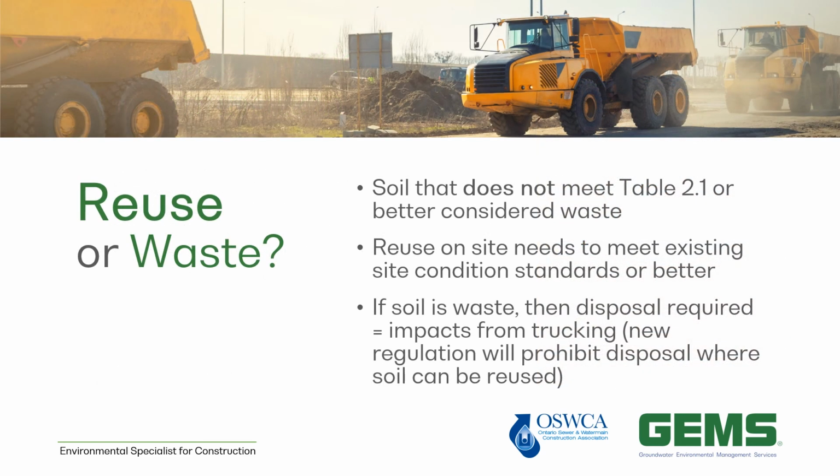Sampling your sites before construction or during construction allows you to know the soil quality and if it meets the reuse criteria or if it needs to be considered as waste for disposal. Any soil that does not meet Table 2.1 or better is going to be considered waste material and would need to be sent to an off-site disposal. Anything that is Table 2.1 or Table 1 can be reused on site. Again, if any soil is considered a waste, then we know there are impacts from trucking and other restrictions that are coming out for disposal and trucking requirements.